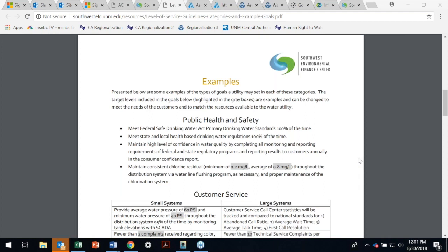So getting the criticality requires you to think of the bigger picture. Is this one critical to keep the whole system running? If so, what kind of maintenance must I do to minimize downtime, to maximize the ability to serve the good water, not cause problems? So you will have to have some kind of maintenance schedule that considers where this pump or pipe or well or tank or whatever it is fits in the bigger picture, and how it is critical to the system.